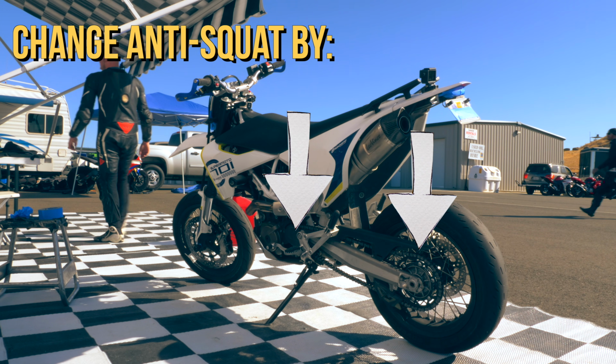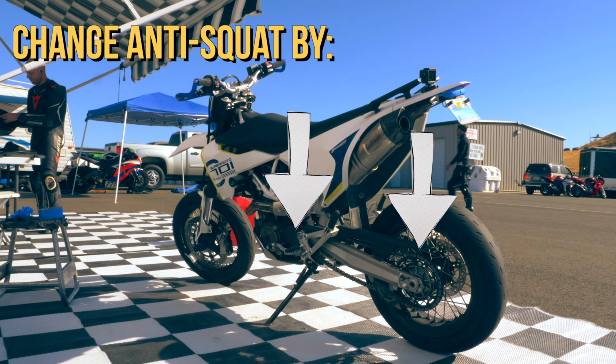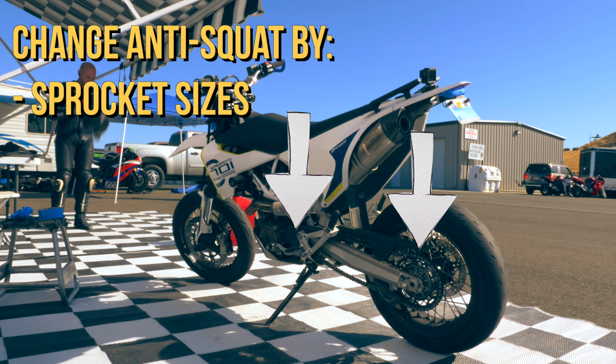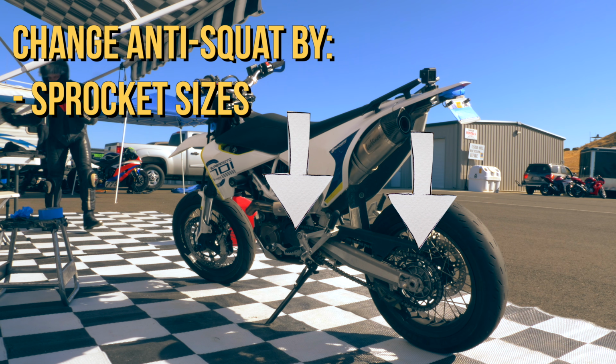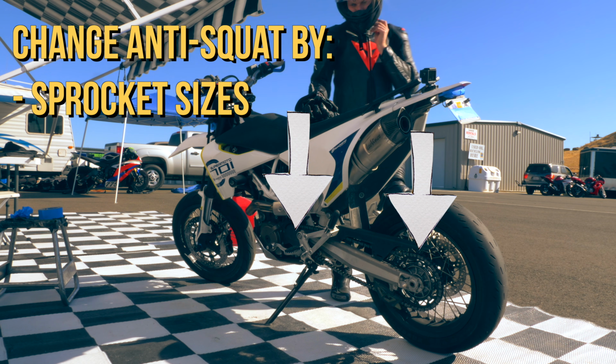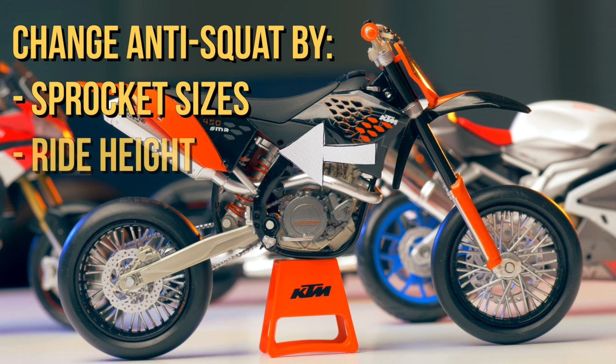If you want to adjust anti-squat, you can do this by changing sprocket sizes front-rear, which changes the chain pull. A smaller front sprocket will provide more anti-squat, and a larger rear will provide some but not as much anti-squat effect, and vice versa. Adjusting the ride height on the rear suspension, which changes the swing arm angle. Taller ride height equals more anti-squat and vice versa.